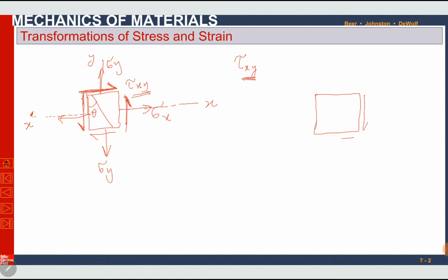But if we see here, like this one, now the plane of this stress is the positive x-axis, this is the positive x direction, and the force is in the negative y direction, downward. So positive, negative, opposite signs. So this tau xy is actually negative. The value is negative, the direction is negative actually.